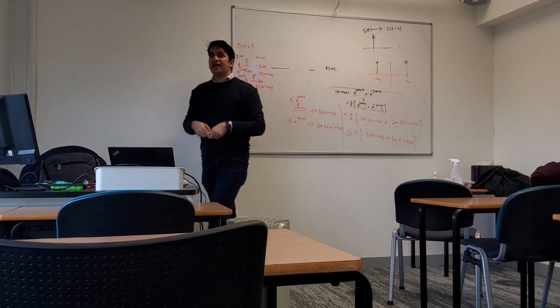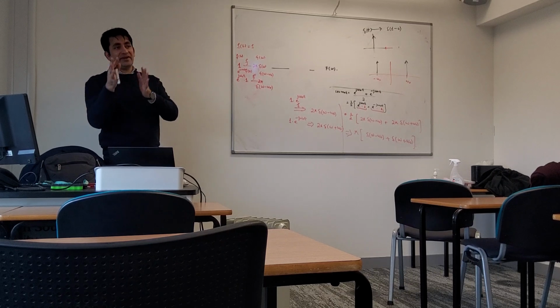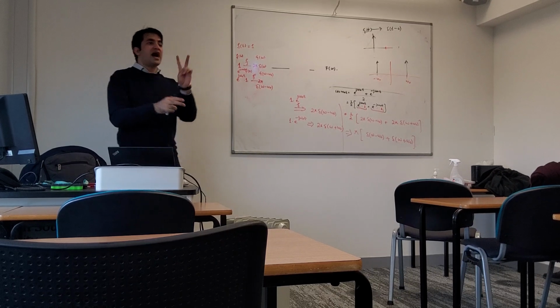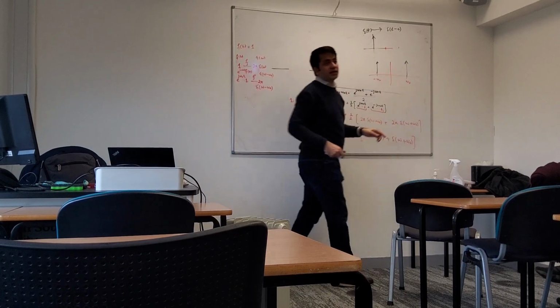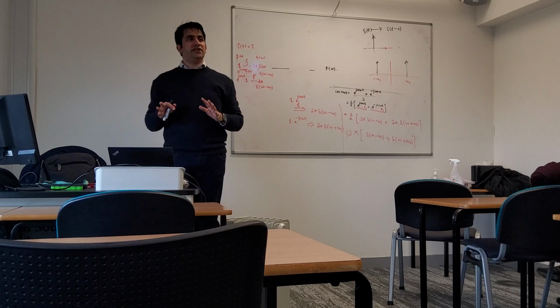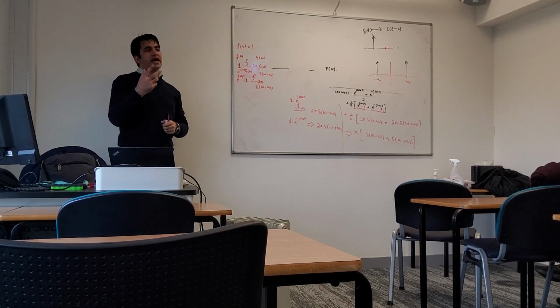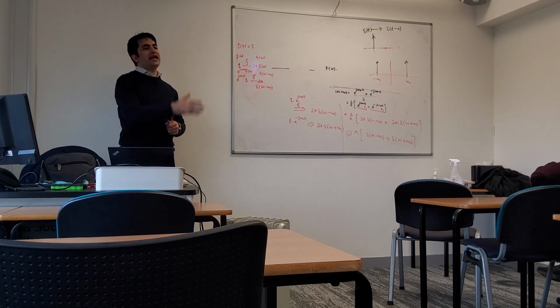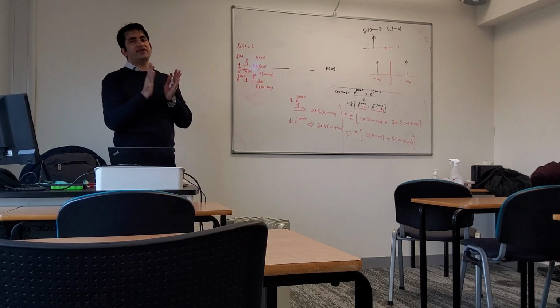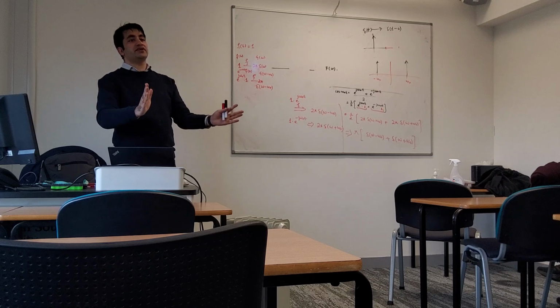So if I want to find the Fourier transform of a cosine wave, I will see only two pulses, one here and one here. And this is aligned with the mathematics of cosine as well: cosine has only one frequency on the positive side and one frequency on the negative side.